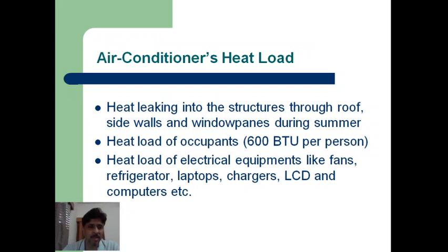The next one is the heat load of electrical appliances. Every appliance emits a certain amount of heat. These days we have a lot of gadgets in our homes, like fans, refrigerators, laptops, chargers, LCD and LED TVs, computers, everything, even electric irons and microwave ovens. All these gadgets add heat load into the refrigerated space, so they should also be taken into consideration while calculating the heat load.